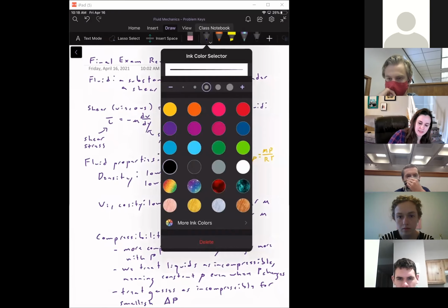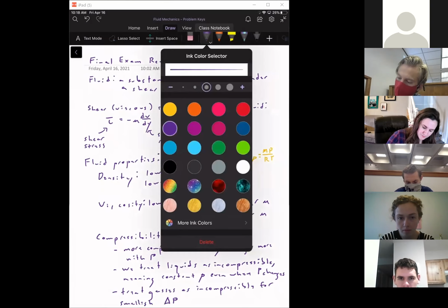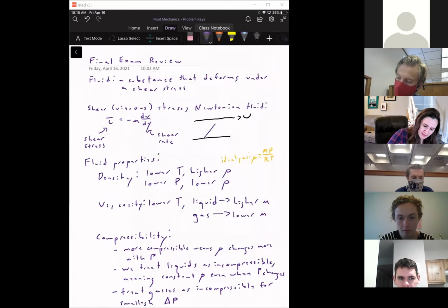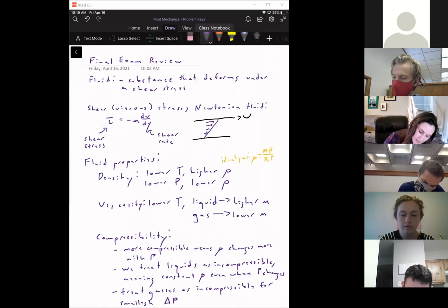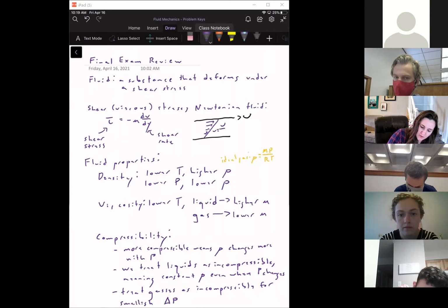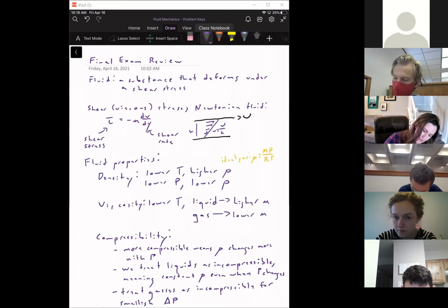But it's there to tell you something. Imagine two plates. One of them is moving, and here's the velocity profile like this. If the top one is moving to the right, then we know the shear stress, okay, and in this case the velocity profile would be u equals big U over H, where H is the distance between them. That's just always what it is for those two plates. And u is positive because it is going from here to here.